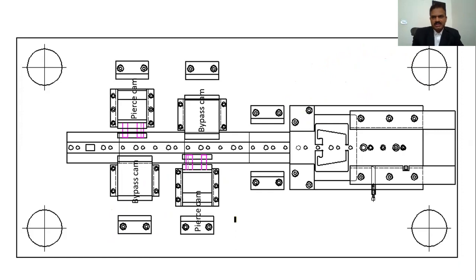All right, so let us just have a general look at the die. This is the bottom half. You'll see a trigger finger here. You see the die here, and this is the bending. This is the heel block, which will support the bending punches, and the punches bending the part. It will stop it from yielding. So this is the heel block.